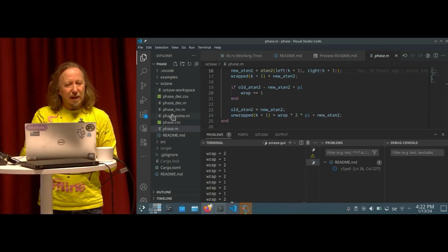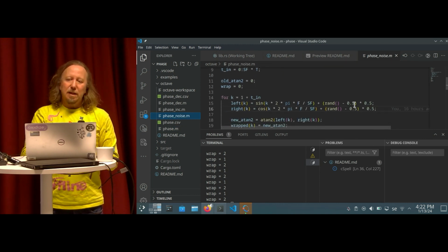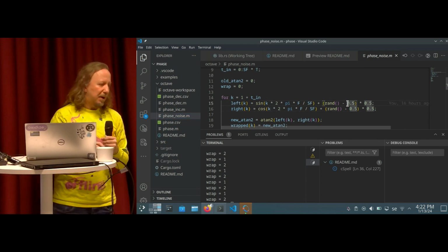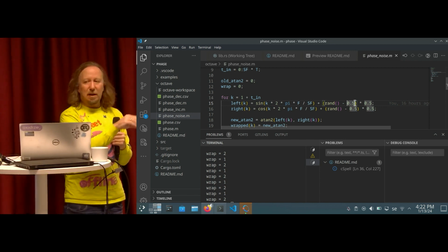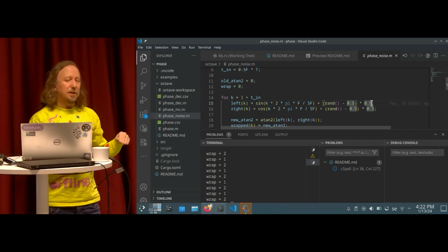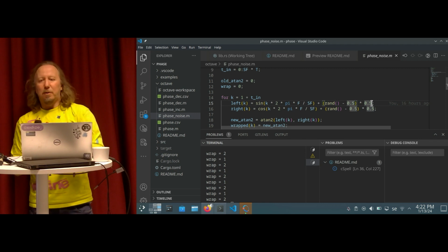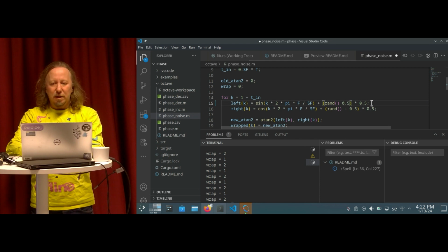This is the phase noise. So let's have a look at how it looks like. Here is just an offset, the rand function gives random values between 0 and 1, so we want to have it centered around 0. And here is the weight. So the signal would go from -1 to 1. That's why 0.5 means that it's 1/4. But let's double the noise to 1 and see how that performs. And now we are really, really noisy, as we will see.